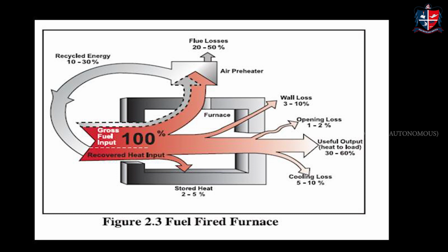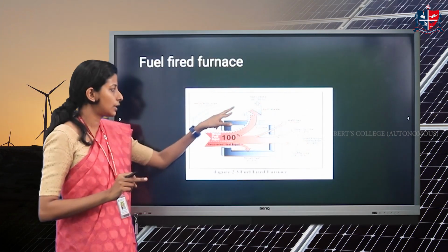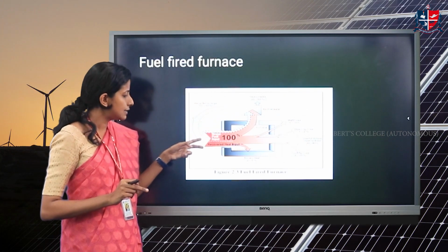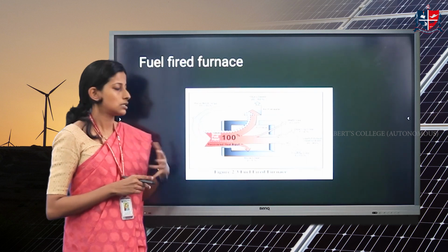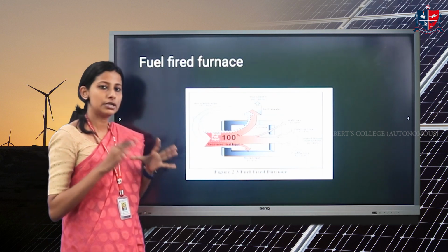To avoid the maximum loss from the flue gas, the heat from the flue gas can be regenerated. That is called recycling. You are recycling the flue gas, and that heat is again given to the fuel for generating heat. I hope the basic function of a furnace is clear to you.